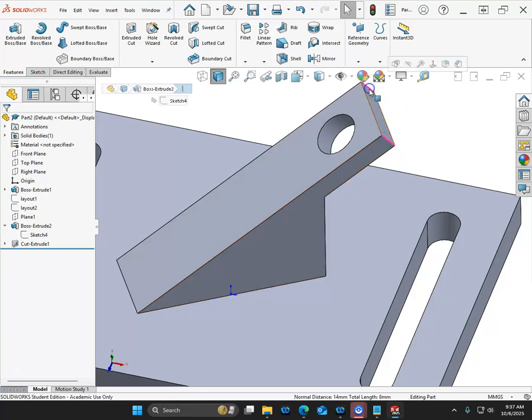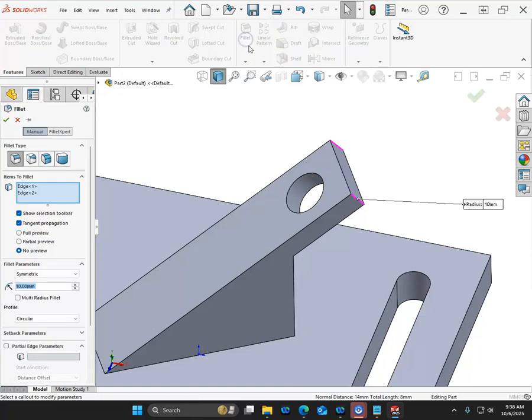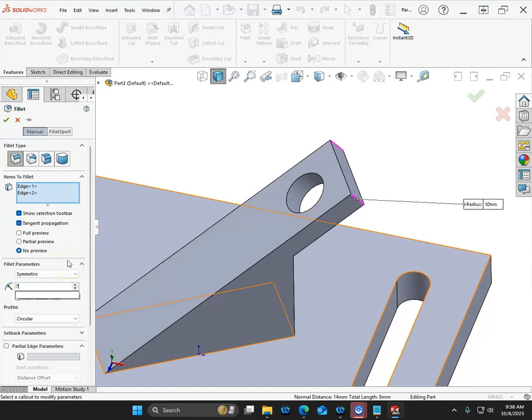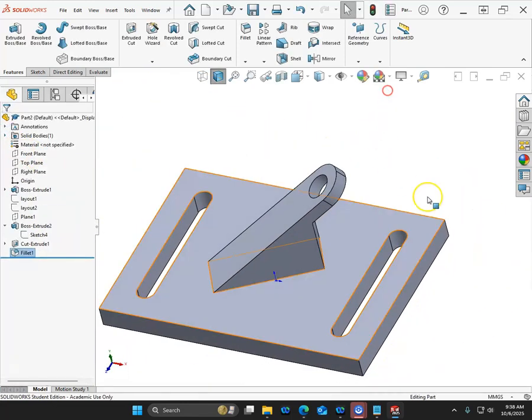If I do the fillet, chances are I'll end up with a separation line between that geometry. And since I bypassed the context menu, we're going to end up with a radius of 7 and see what that looks like. All right, so we have point, point, and the point.